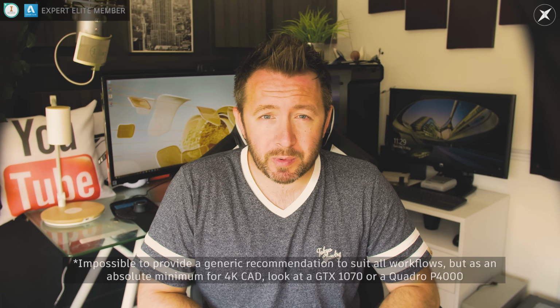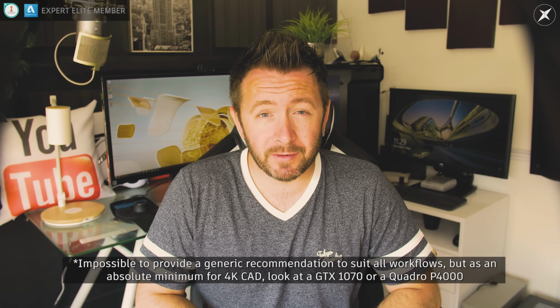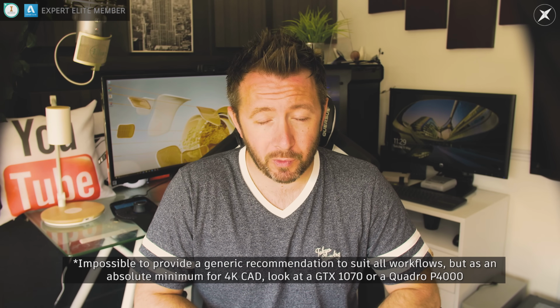And lastly, the absolute bottom line here is that 1920 by 1080 resolution requires your system graphics card and CPU to deliver just over 2 million pixels to the monitor, whereas 4K sees your system hardware calculating, handling and delivering over 8 million pixels to the monitor. And in CAD, that's a heavy burden on the hardware. Higher end current gen hardware should cope with it, but low end parts will tangibly struggle to deliver a smooth visual experience if you're running 4K resolution.